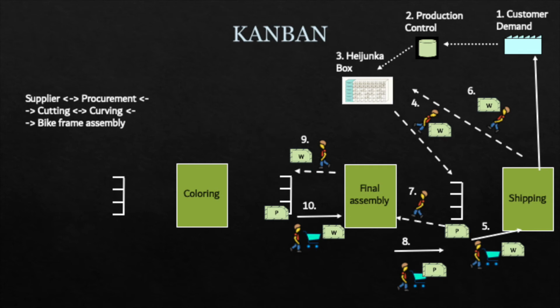Then the milk runner will identify the right colored bike frame according to his withdrawal Kanban, will remove the production Kanban that is attached to the bike frame, will attach the withdrawal Kanban he just brought from the final assembly area, and will carry the bike frame with the withdrawal Kanban attached to the final assembly area. With the use of the Kanban cards, the communication flows from the final customer all the way to the metal pipe supplier and ensures that only the amount and the type of bike is produced that is actually needed.